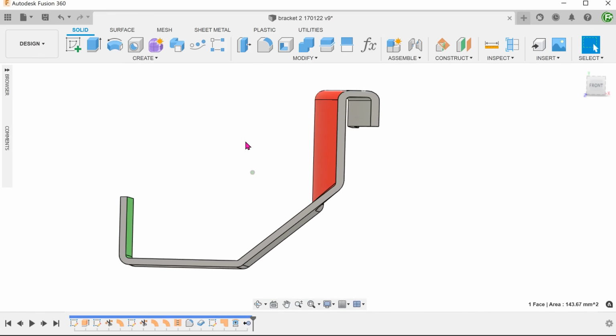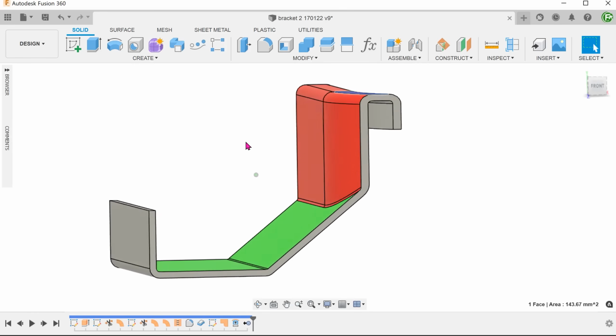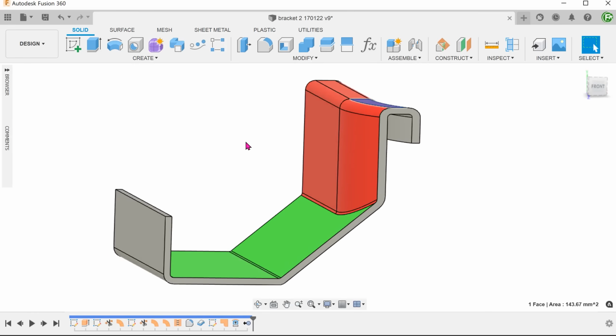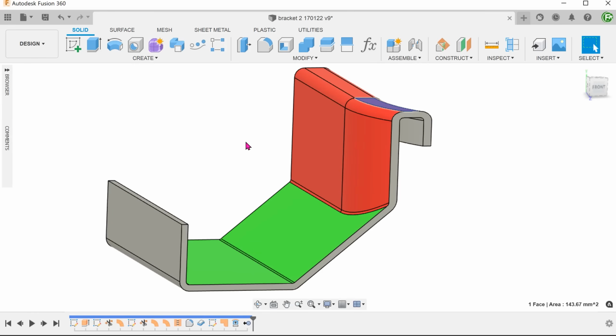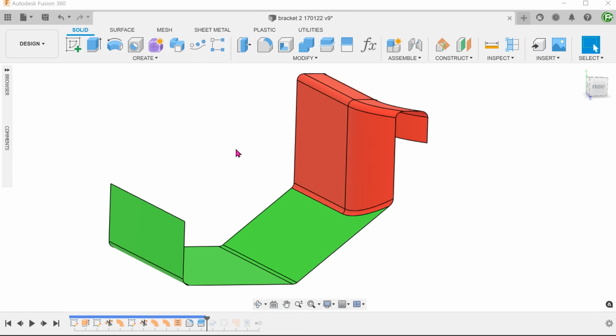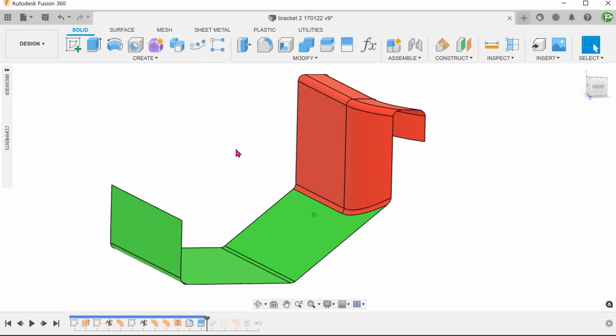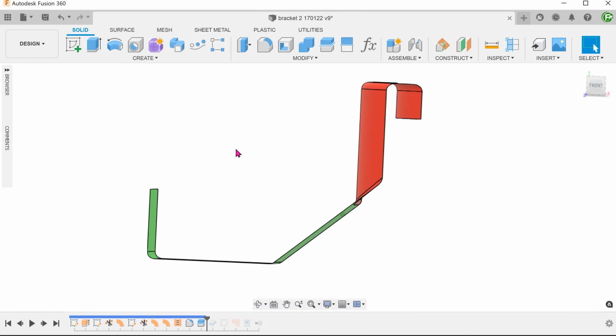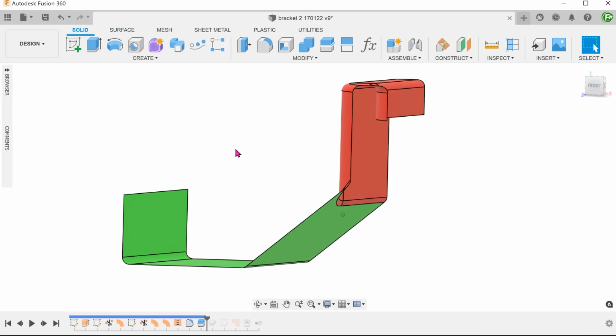If you are familiar with this channel, you will know that I am quite a big advocate of using sheet features wherever possible. The use of these features greatly simplifies sketches. They also tend to be much easier to fillet, as we shall see later. In my opinion, the biggest benefit of employing sheet features is that it helps in the thinking or ideation process. When you are able to envisage a model without its thickness, it is easier to visualize and plan the modeling process. In this video, we will see how we can create this with surfaces and thicken.